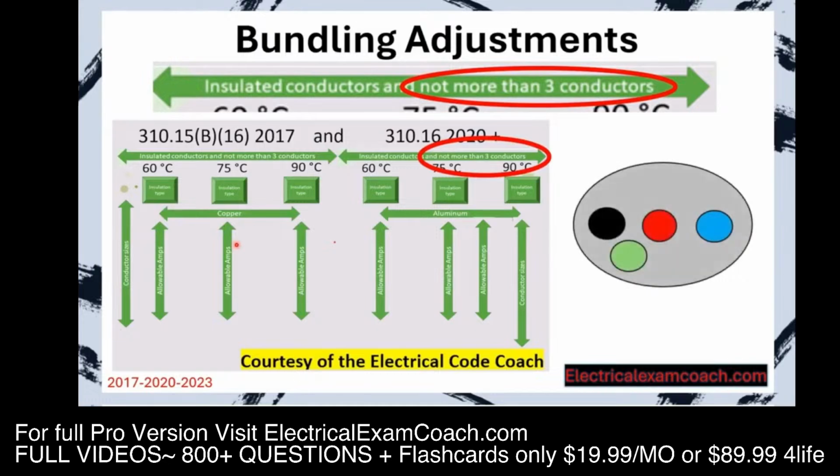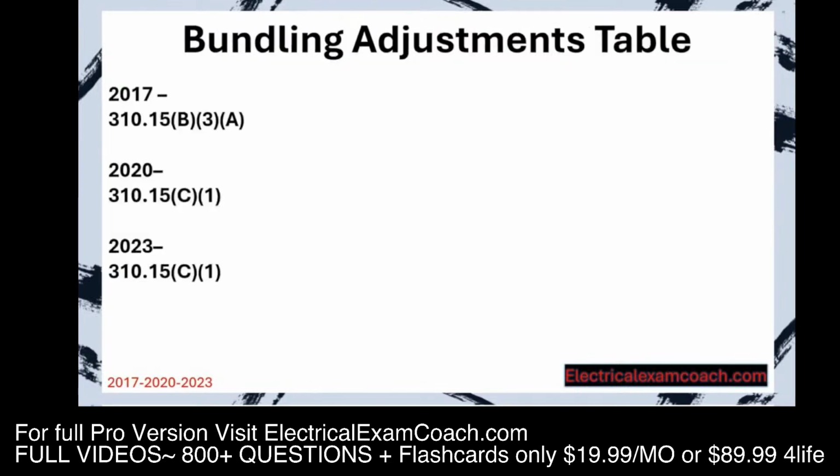Let's take a look at it. Let's imagine that we have a piece of conduit here and we pulled in a black, red, blue, and an equipment grounding conductor. What this table is saying is that those ampacity values listed down below in this table are true as long as you have not more than 3 current carrying conductors in a cable, pipe, or raceway. If you do have more than that, then we have to do what's called a bundling adjustment. Let's learn about our bundling adjustment table.